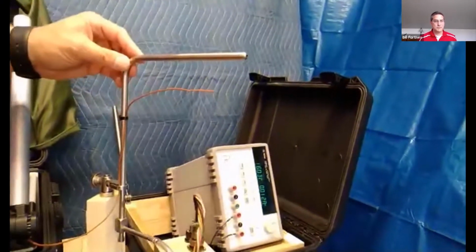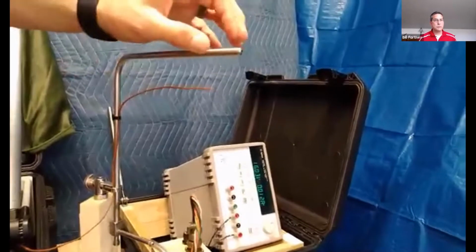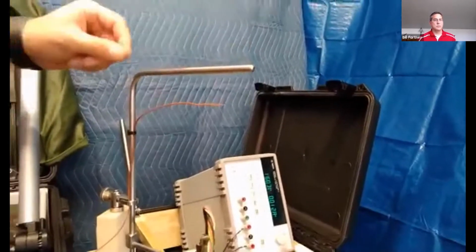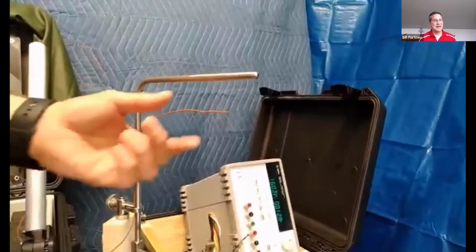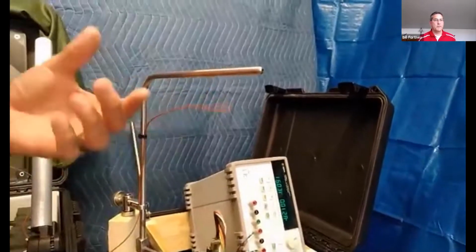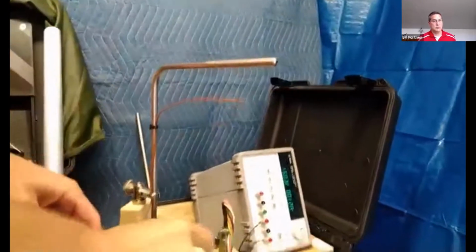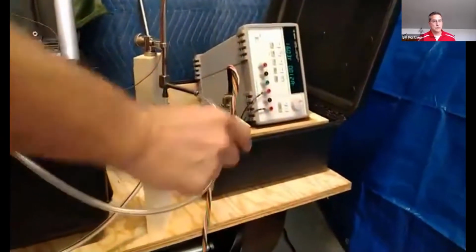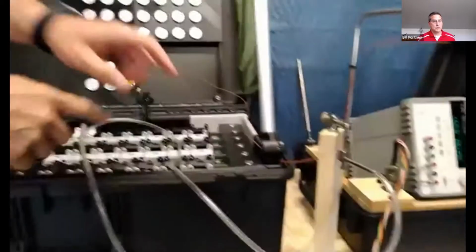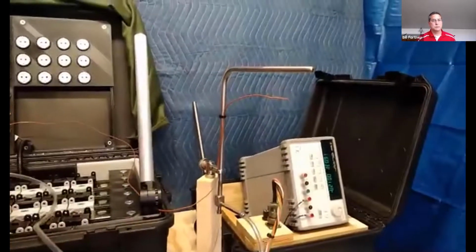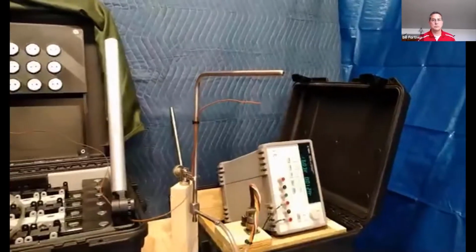These are the sensors that will be attached to the rake. At the top here, this is a pitot tube. It measures change in pressure, and this is a thermocouple. It measures the temperature, similar to a thermometer. When air blows through here, it's going to come down to these tubes right here and travel back into our data acquisition case, and that information will be relayed to the computer.